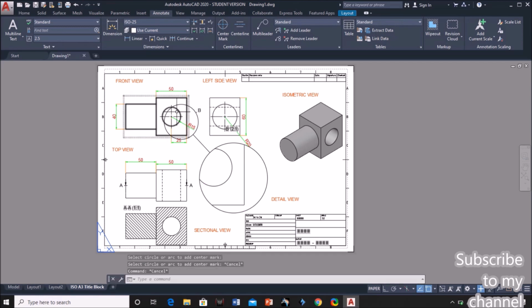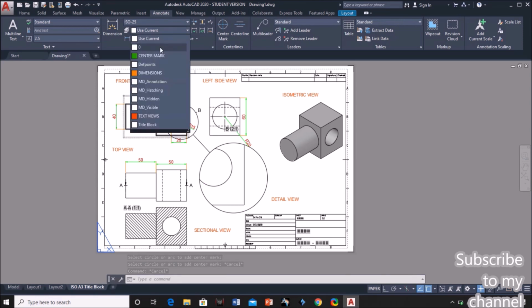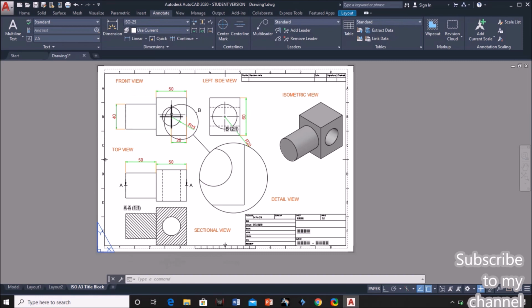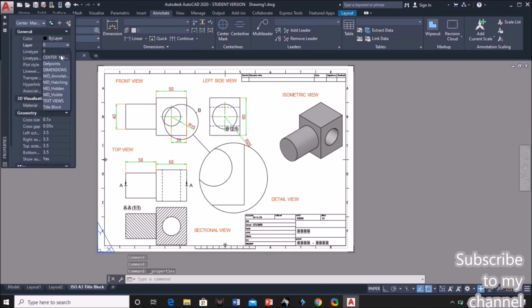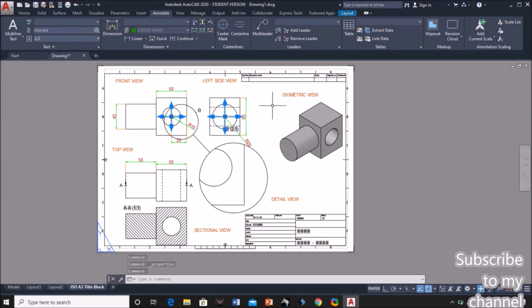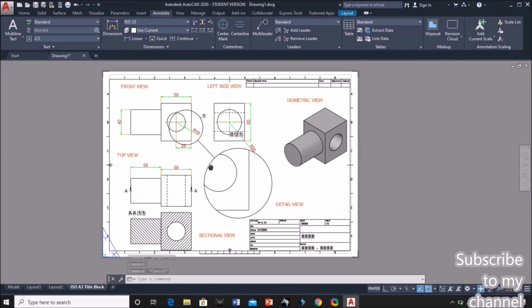Now I need to convert the center mark to another layer, that is the center mark. So for that select the center mark. Go to layers, or else you can right click it, go to properties. Now select the layer as center mark. So these marks are converted to one layer, that is center mark. So this is about the complete conversion of 3D object into a 2D object, either in first angle or third angle projection.